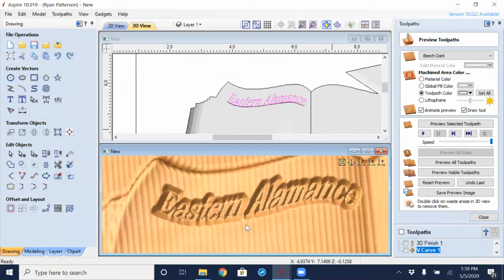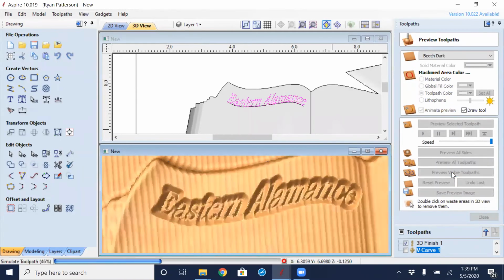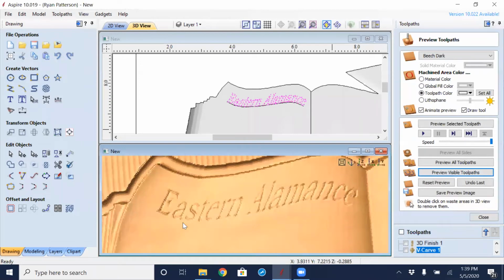Still want to be a little bit clean with it, but you could be a little bit sloppy. And as long as you're using a material or wood that doesn't bleed as much, you might want to put some lacquer, some sort of varnish over top of it first to help seal the wood from bleeding out. But now if we ran the finishing toolpath, it kind of comes through and it would have removed and knocked off the paint that we were messy about and only left the paint in the untouched areas of that VCarving.